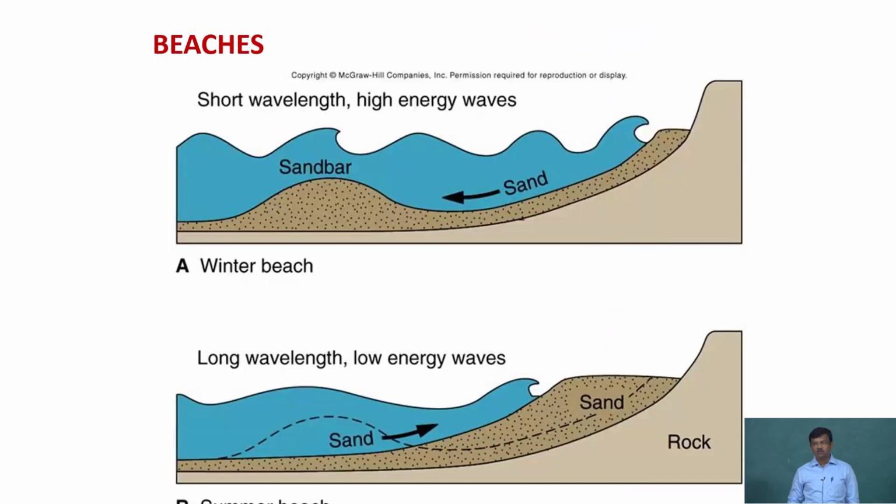Now, knowing what your driving force is, what the sediment transport is, or how the sediment is moving, consider a short wave with high energy. Energy is always expressed in terms of the wave height, correct? Energy is proportional to H squared, and a short wave always makes the shoaling effect, and it always goes up to the breaking. Breaking also makes a lot of energy loss, or energy release, into the system, which means it can advect a lot of sediment.